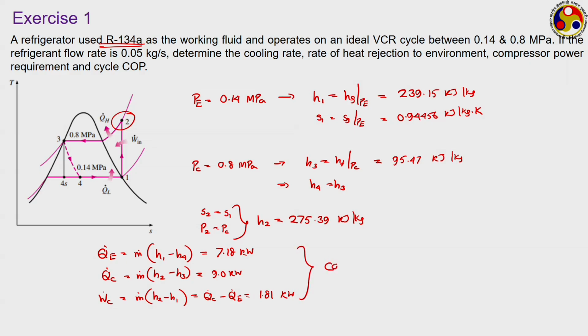if you combine this, your COP, which is Q dot E divided by the compression work, that will be coming something like 3.97. So, for every unit of compression work input, you are going to get about 4 times refrigeration effect for this. So, and I am leaving one task to you.